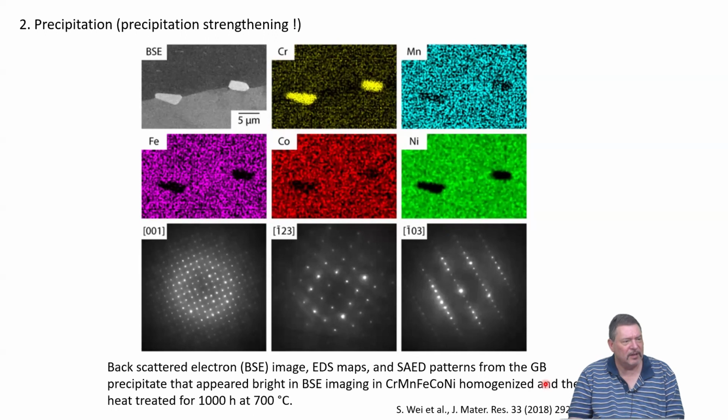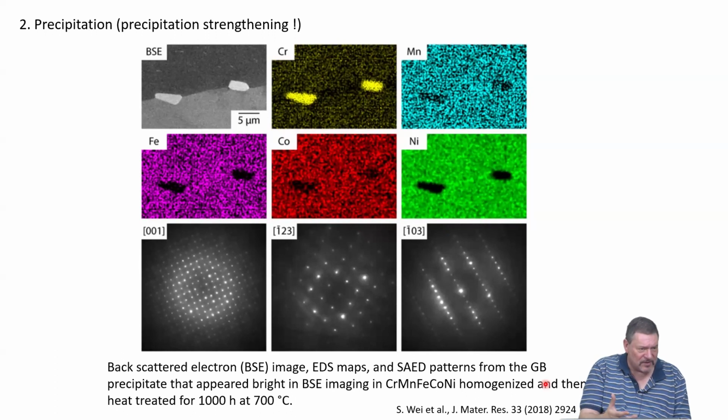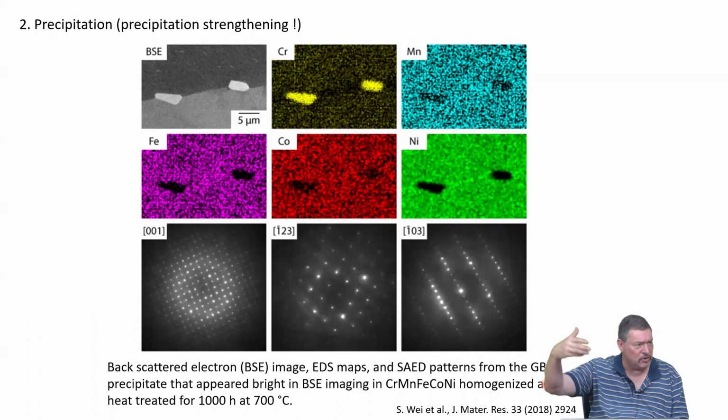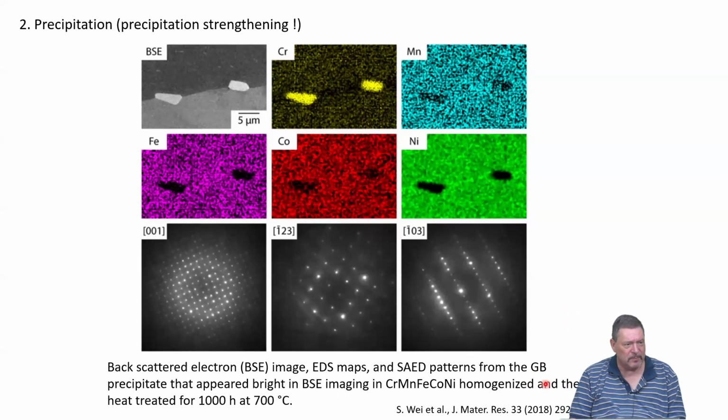And mostly they form first at the grain boundaries, because there is higher mobility, and also the accommodation of a new phase can be easier when that phase is still very small, in the nucleating stage. So stresses are not as high, and stresses give you an additional free enthalpy penalty. So that adds up to the height of the activation barrier, and this is why these places, dislocation cores, grain boundaries, are preferred nucleation sites for the second phases that form, which can be used to your advantage.